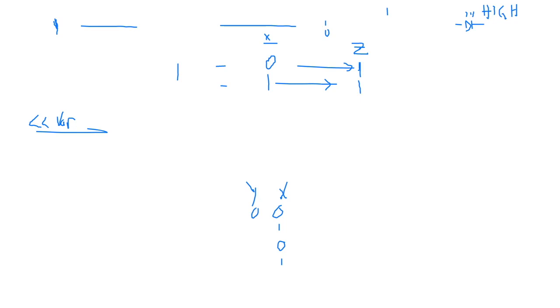And then Y changes from 0, 0, 1, 1. Now we say there's no way that this is going to be a 0, but we don't care anyway. It should be a 1, and this should be a 1. So simply it becomes an OR gate. Well spotted, Arathi. So it becomes an OR gate.